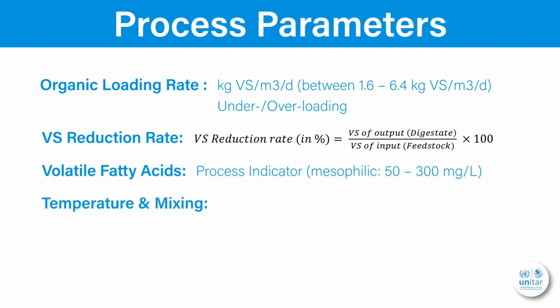The temperature is also an important process parameter. Ideally, we have an online measurement of the digestate temperature to make sure that it is as constant as possible and within the designed range of mesophilic or thermophilic conditions. Otherwise, spot measurements of the temperature with sampling valves are also possible. A temperature profile across the digester can help us determine if the digester is well mixed. Varying temperatures along the digester profile tell us that the content is not mixed properly, and we might need to investigate the issue.